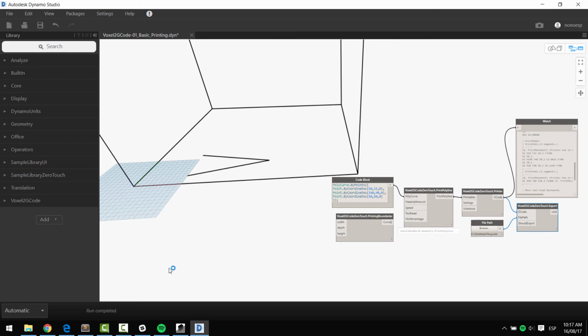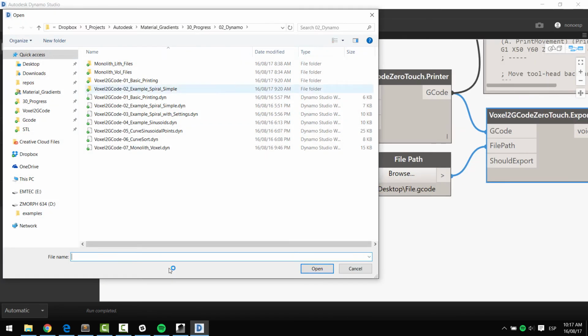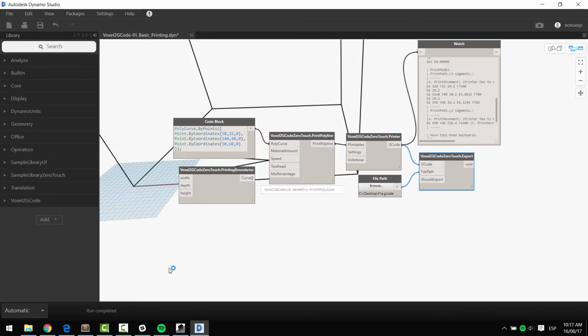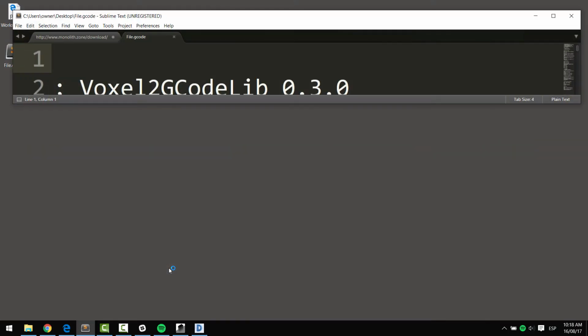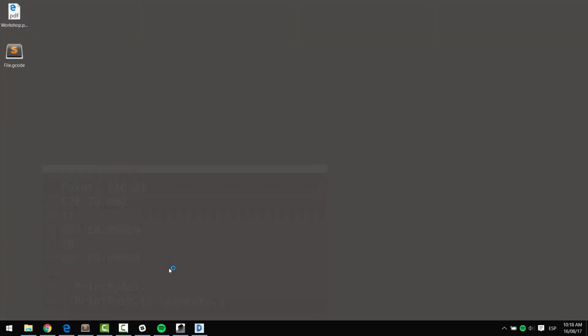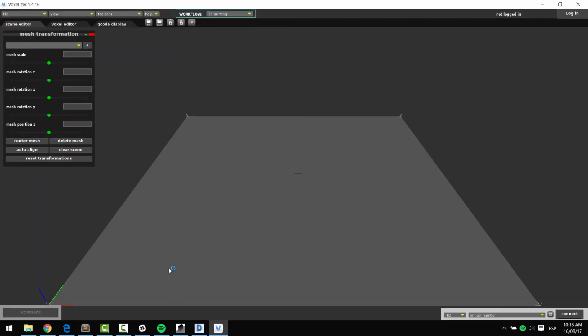So this example I prepared because once you give a path to it, so now I have it on the desktop, every time you change this model, it will basically spit out some G-code that we have here, and this would be already a 3D printable G-code file, hopefully. So I'm going to go ahead and do this quick test because we can. The first thing, I'm heating the extruder head, which with PLA gets up to 200 degrees, and the heated bed gets up to 60 degrees.